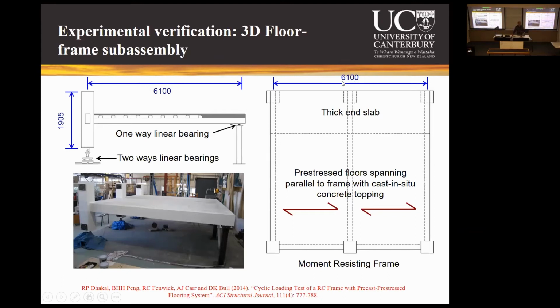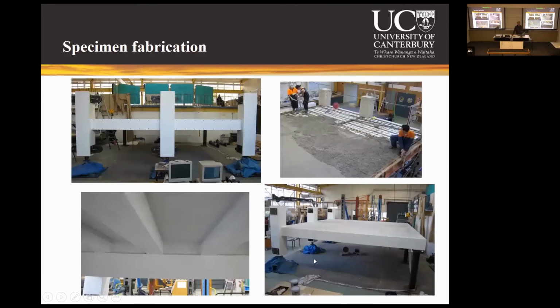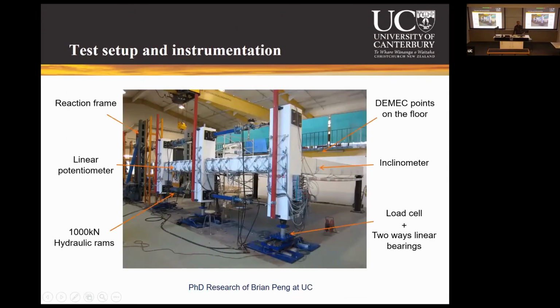We have a 6.1 meter by 6.1 meter 3D frame floor subassembly. The details are given in that paper. These are some of the photos during the preparation of that specimen, and this is the instrumentation. We were testing it in cyclic loading, and measuring all the deformation in the columns and beams, and also on the floors, to see the floor deformation and measure the cracks on the floor.